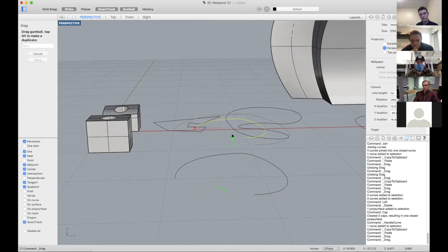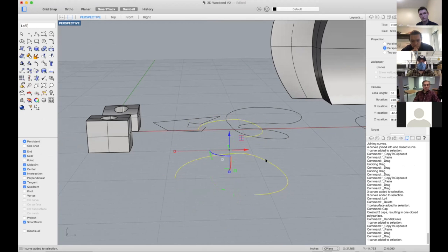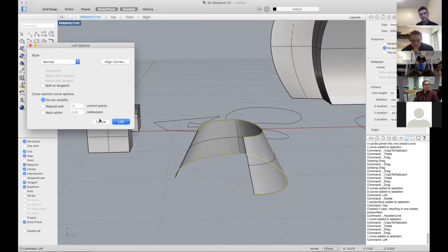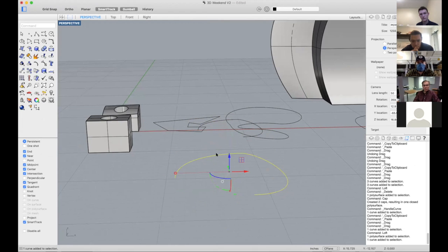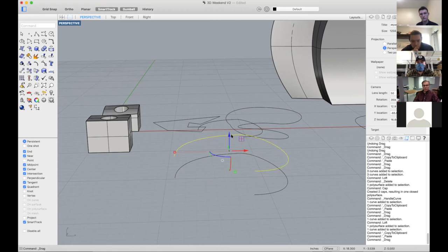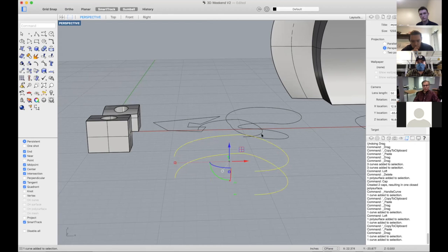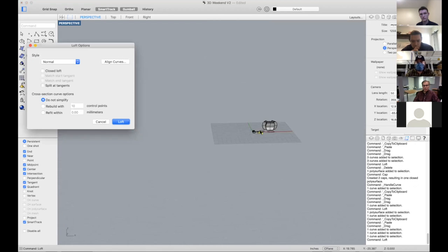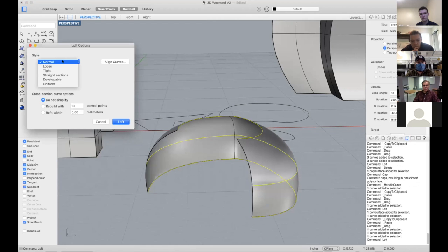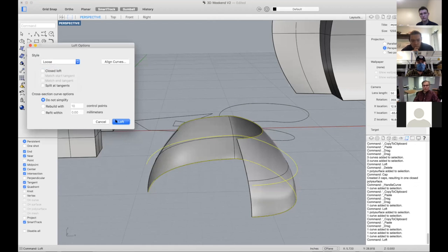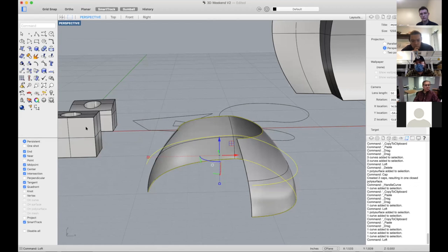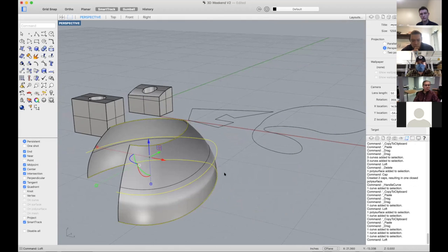I can make something really complicated like this. Well, here, let me draw another one in there just to demonstrate. Yeah, so I can make something that can be used as a very complex cutting tool, and then use that to cut away at a block and create a very complex profile pretty easily using that split and Boolean split and things like that. Again, everything comes down to Boolean operators: your Boolean split, your Boolean union, and your Boolean difference.